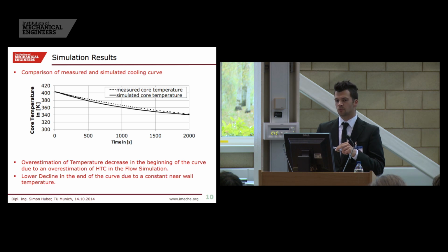I cannot cool down more than this temperature. So I have to change the reference temperature for the heat transfer coefficient, and I can easily calculate the physical heat transfer coefficient by the definition, and now I get a quite better result for the two cooling curves.